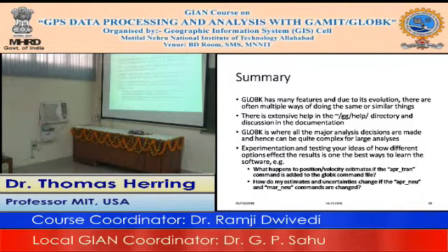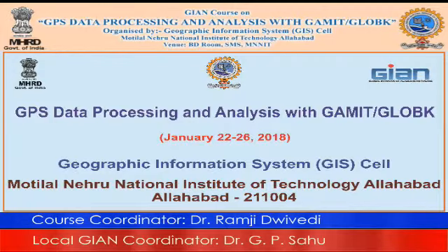Sir, when we call for any GLOBK operation by typing APR_XXX, if you are giving any U, then it will take parameters in the state vector accordingly, or every parameter is taken. So when you say APR northeast up, the next thing you give it is either the name of a station or all. And if you say all, then the next set of values you give it will be applied to all stations.